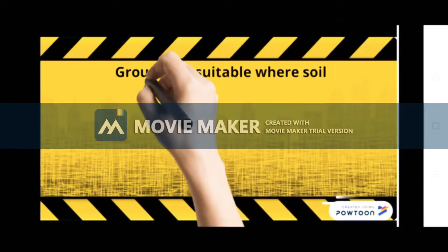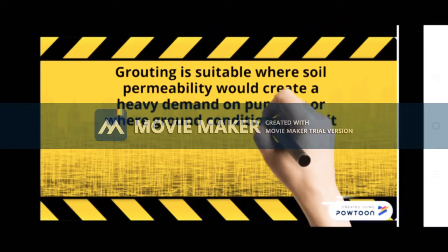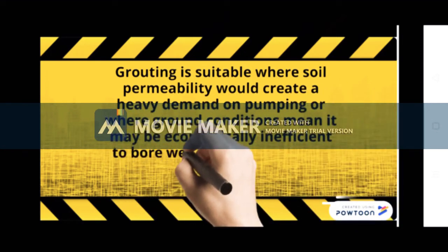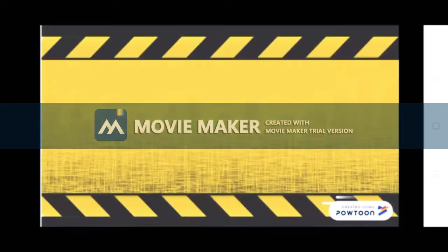Grouting is suitable where soil permeability would create a heavy demand on pumping or where ground conditions mean it may be economically inefficient to bore wells. There are several different types of material used for grouting.